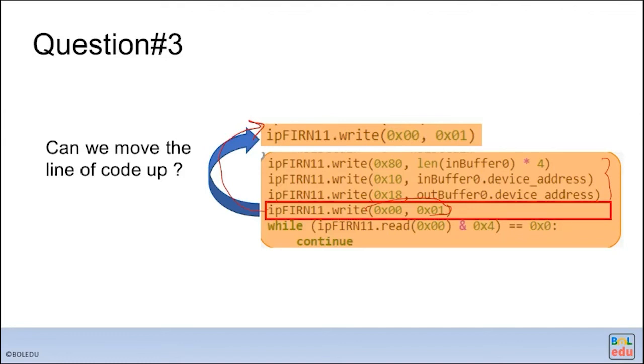Okay. Remember, for AXI Lite we use it first for configuration, or small amounts of data. For audio and video, those are streaming data, so you should use the DMA. Suppose you have an audio file loaded into the DDR memory, and the native data is only 24 bits.